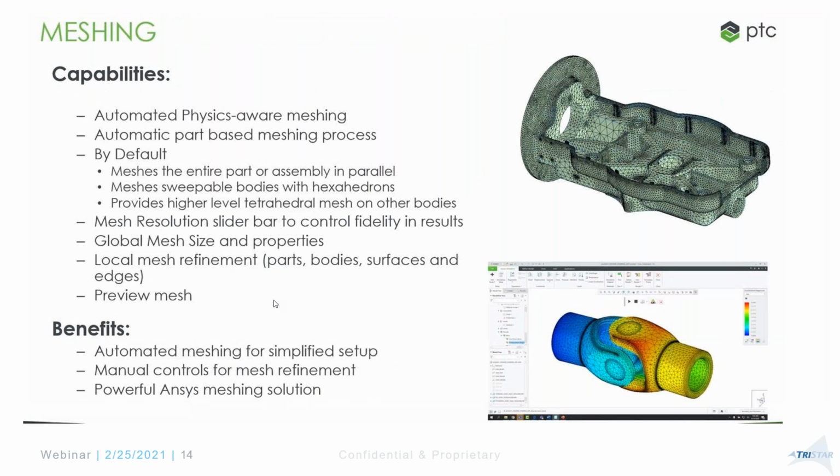Right? And then meshing itself. We all know that FEA, finite element analysis, is all about divide and conquer, right? All you're really doing is taking a structure and dividing it into tiny, manageable structures, what we call mesh, elements and nodes, as you all know. And then you're using your algorithm to solve for deflection, stresses, temperature, modal frequency, etc. Right? So that's the key basics of FEA. In an H-element code like ANSYS, the finer the mesh, the more accurate the solution.